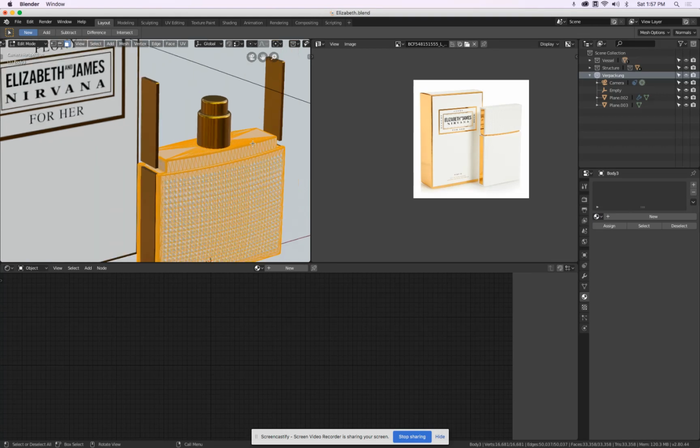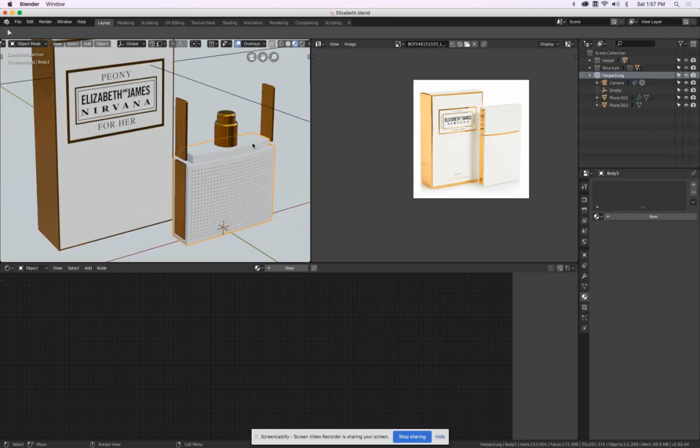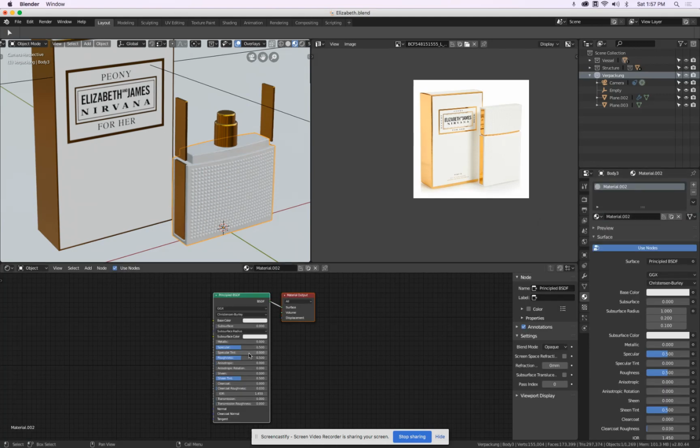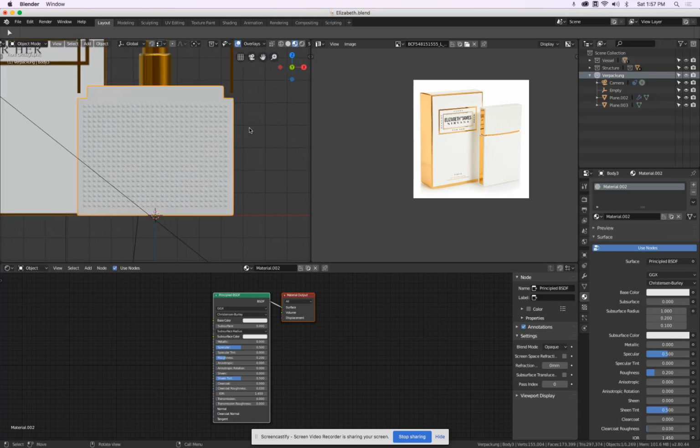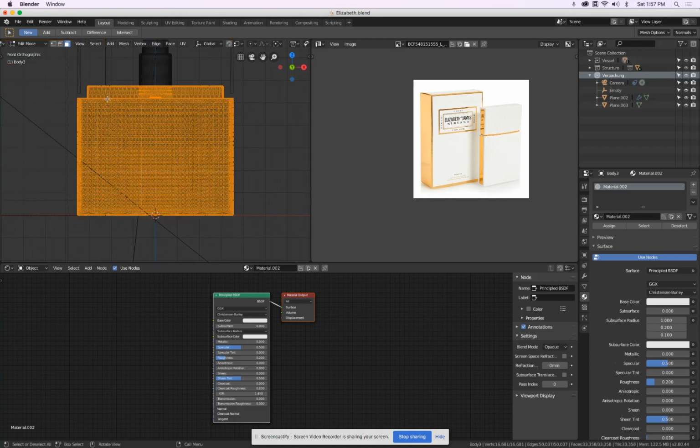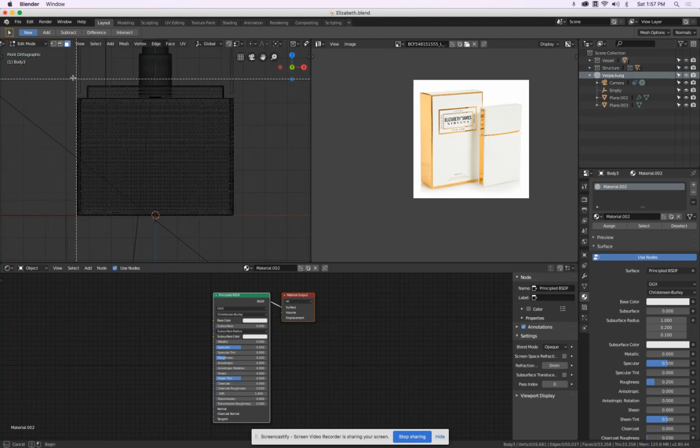And in my case, I see they are fused together. Never mind, that's good. So let's make new. There's our plastic material. 0.2. And then I go to a front view, go to edit mode, go to wireframe, A A, and press B and select all these, I'm in face mode, all these faces on top.